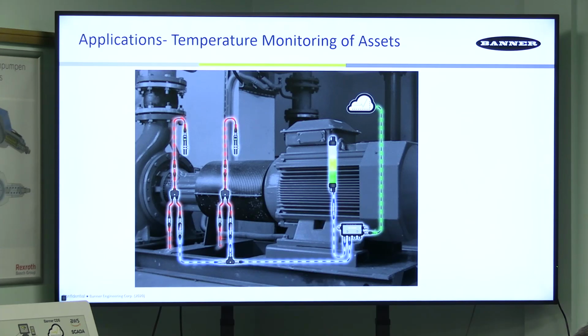There's another view, where we're monitoring the temperature via infrared with those 2 sensors there, and then making it a unified Modbus signal, which is demonstrated by the blue, feeding it into the controller, and then outputting back to the Modbus light. So you know that if it's amber, you might want to plan something in. Goes red, there's a catastrophe about to happen.